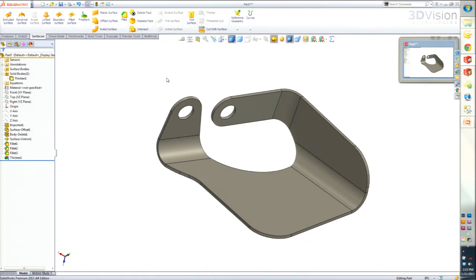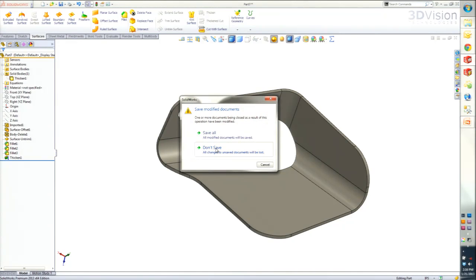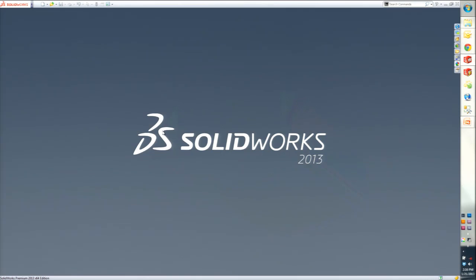Can I now change the radius? What's that? Can I now change the radius so that I have a specified radius there? Yeah, exactly. I could edit any one of these individual fillet features if I wanted to change that radius. Okay. Would that work without the untrim? Like, did you have to untrim that, or could you fillet it straight from the faces?